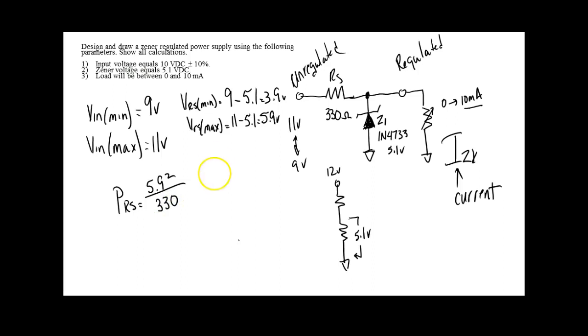And that's one of those Watt's Law formulas you should know. What are our three Watt's Law formulas? Power in the resistor would be equal to V times I. Power in the resistor would be equal to I squared R. Power in the resistor would be equal to V squared over R. So those are three power formulas you need to know. And these are not on the formula sheet. Why aren't they on the formula sheet? Because you're supposed to know these, right? Basically the only things on the formula sheets are the new formulas that you pick up this semester.